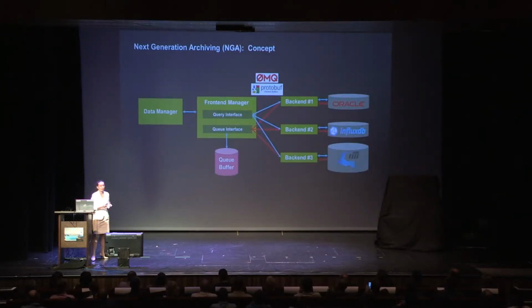Next generation archiving, or archiving for WinCC. Originally, we started looking at newest database technology to see how we can take advantage of it, namely NoSQL databases for WinCC. In the meantime, we decided that we not only want to use these new technologies, but also want to bring in more flexibility in our archiving. So together with CERN, as part of CERN's Open Lab research activities, we work on this next generation archiver, and also together with CERN, we came up with the architecture that you see here.